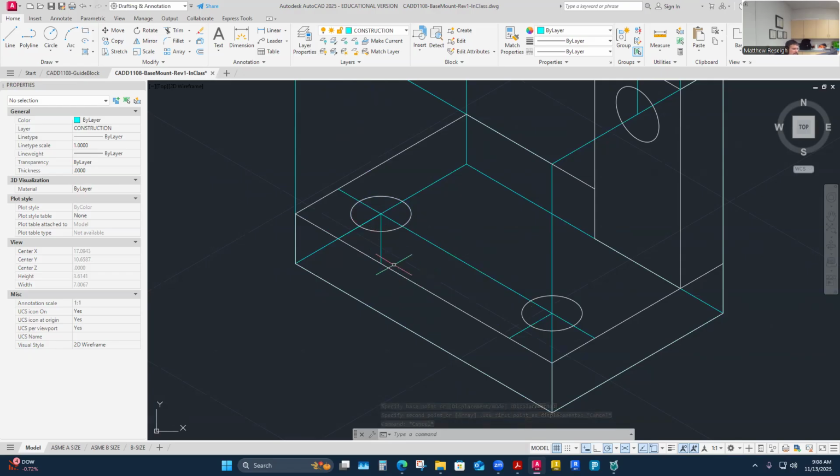And then we need an iso circle for the radius here, or elliptical arc iso. I'm probably clumsier with that, but it's on the same top plane. I'm going to do the iso full circle for the radius, which is a 1/2 inch radius from this center point. Or you can just pull this out. That is a 1/2 inch if I've drawn this correctly, which looks like I have. I just snap to this so I can see my 1/2 inch grid. So there's that one.